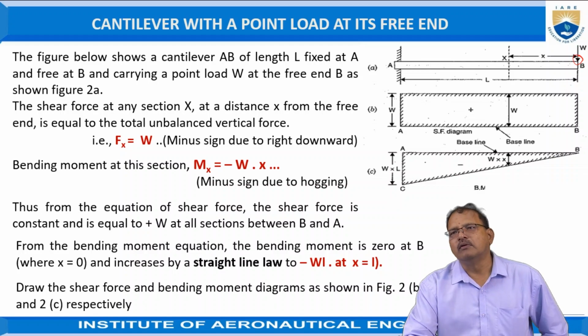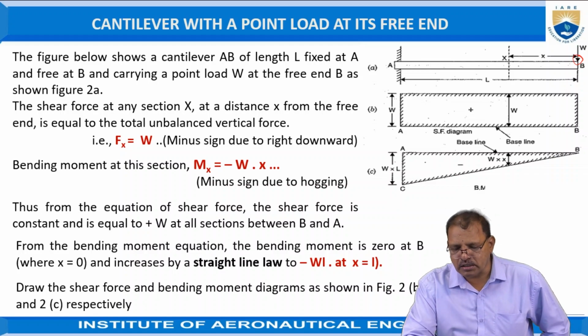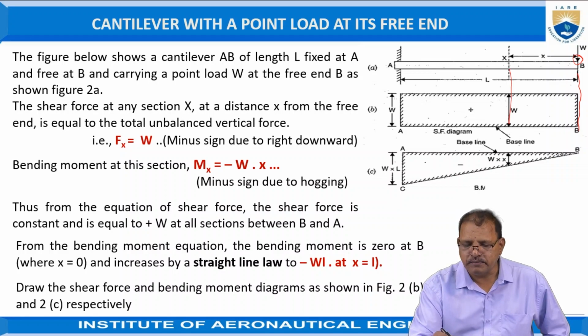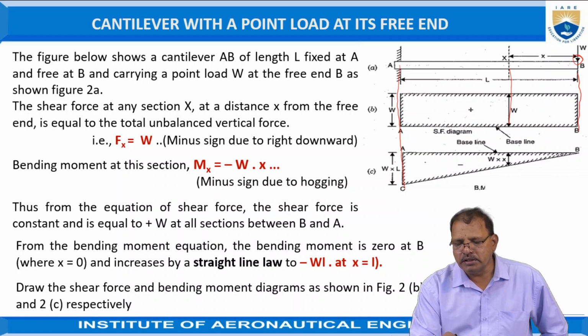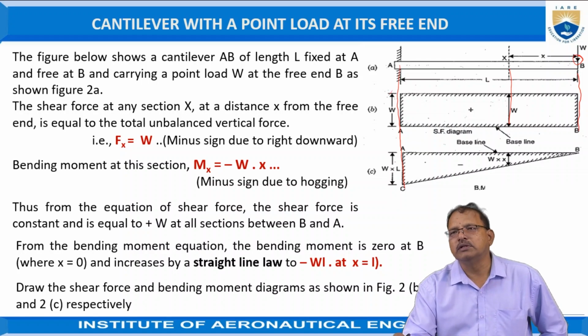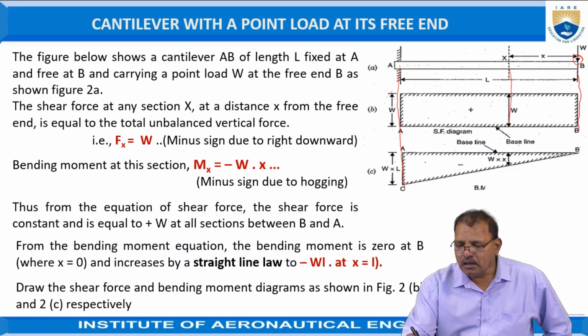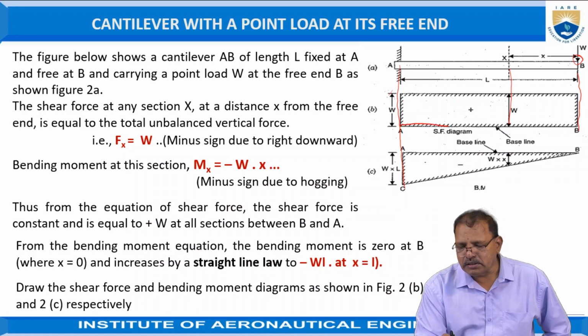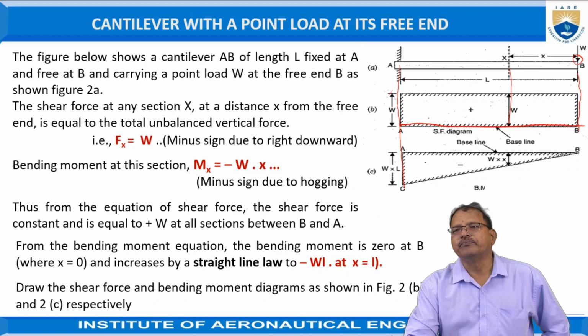That means, while representing the shear force diagram, first of all, draw vertical lines passing through the various key points of the beam in downward directions. Here, the distance between these two parallel lines is equal to the length of the beam. AB is representing the length of the beam.